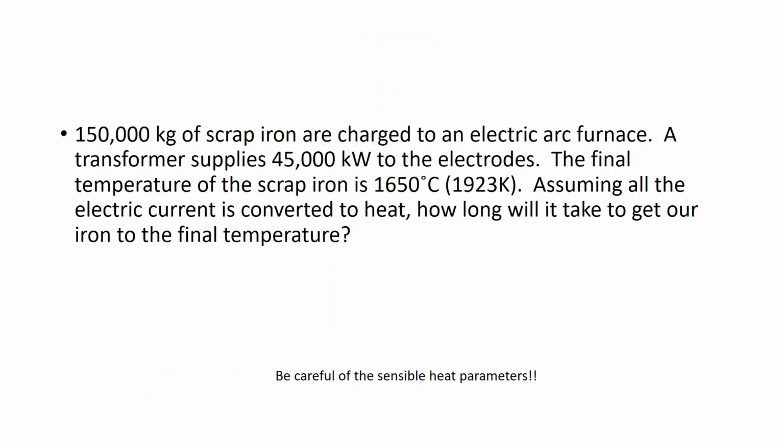So we have 150,000 kilograms, or 150 metric tons, of scrap iron, and we're charging it to an electric arc furnace. We have this electric transformer supplying 45,000 kilowatts to the electrodes. The final temperature of the scrap iron is 1650 C, or more to our liking, 1923 Kelvin. We're going to assume all the electric current is converted to heat, and how long will it take to get our iron to the final temperature? Let's work this one out, shall we?